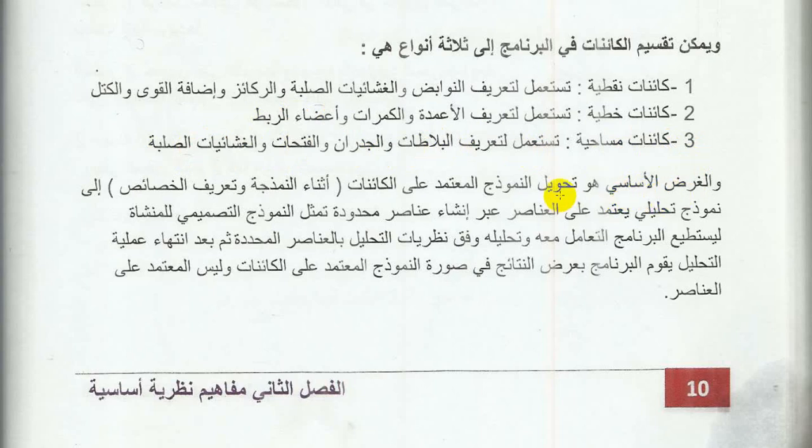The main purpose of converting the entity model while modelling and identifying the characteristics is to form an element-based analytical model, by forming different special elements representing the typical model of the facility. So the software can deal with and analyze the entire model according to the analysis theories with definite elements. After the analyzing process, the program will display results in the form of an entity-based model rather than the element-based model.